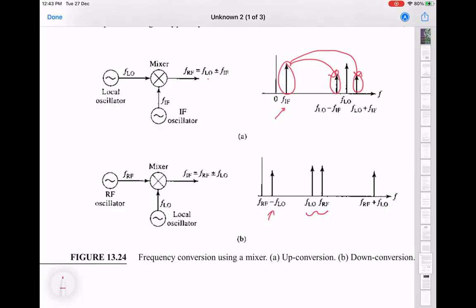In most typical cases, the sum is actually not even passed through because the analog response of the mixer naturally has a low pass filter in it. But otherwise, you usually put a low pass filter because in the down conversion mode, it's the low frequency part of the signal which you are interested in. The information contained in the high frequency is also exactly identical, just like it was there. But you don't worry about it. It's the same duplicate information. So you worry about the low frequency part.